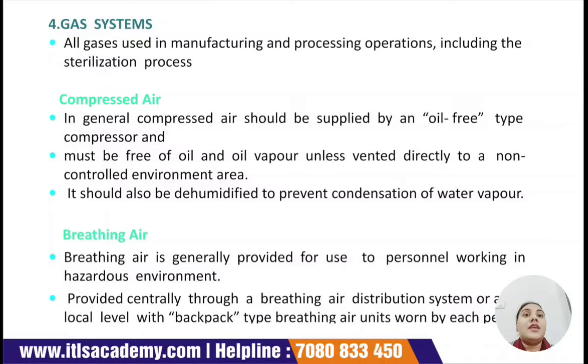Now comes the compressed air. In general, compressed air should be supplied by an oil free type compressor, and must be free of oil and oil vapor unless vented directly to a non controlled environment area. It should also be dehumidified to prevent condensation of water vapor. So what is compressed air?